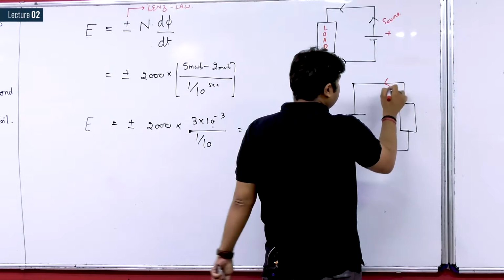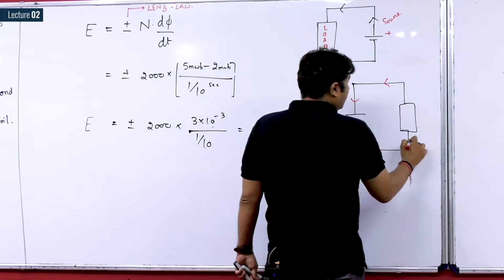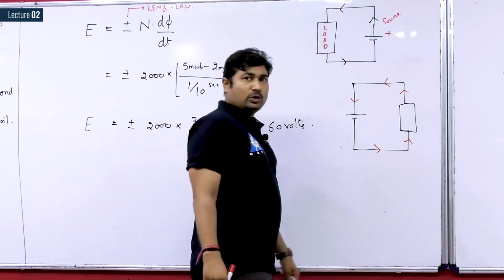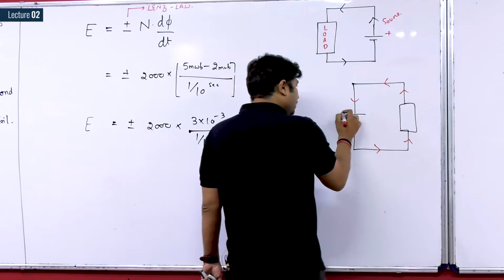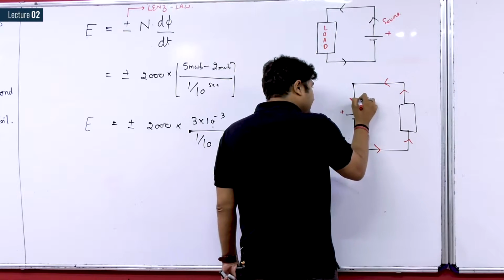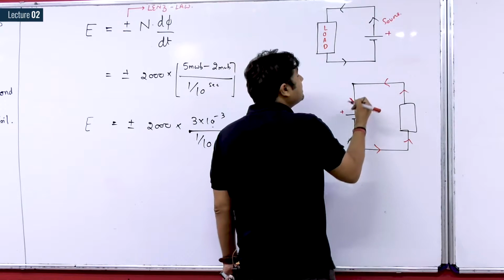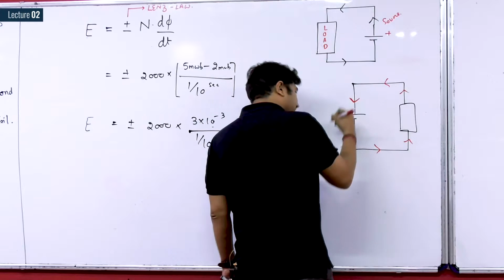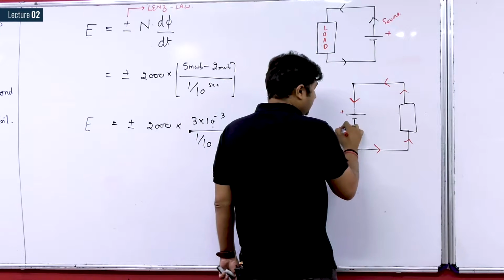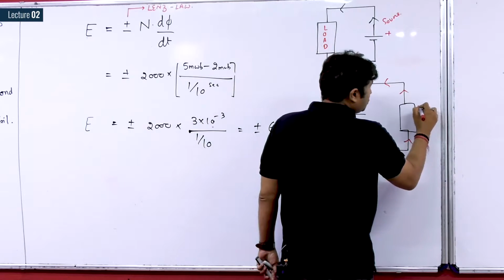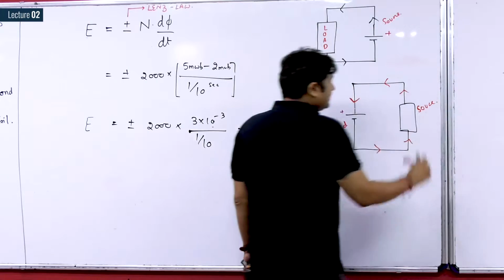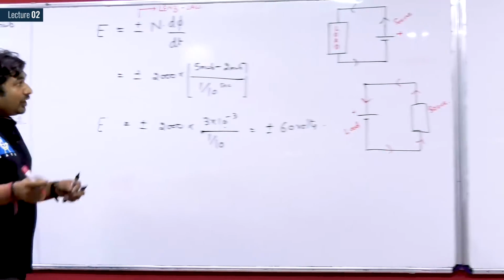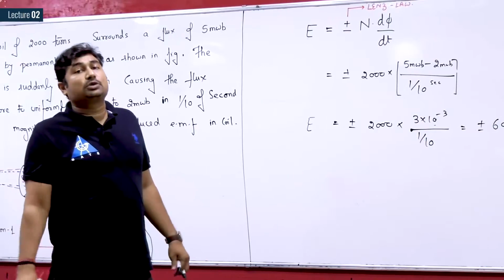Again observe, let us suppose we have two electrical components represented in this fashion. If the current direction is represented in this fashion, now which one is a source and which one is a load? One can say, sir, because of the positive polarity, current is coming in. So it means this appears to be a battery that is charging. So, you can say this to be the load now and this to be the source now. So, from the direction of current we can find the source and load.